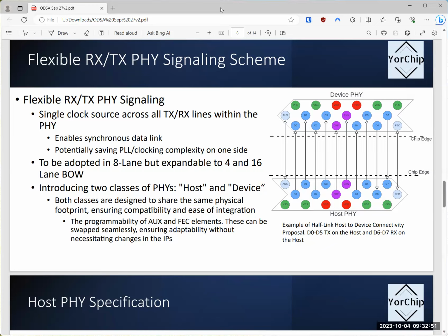The 2 caveats are that there are 2 extra bumps, so it's 12 bumps instead of 10, and that the first step in the spec may not be one side taking the recovered receive clock and looping it back in to create the transmit clock. Somebody could just decide to do that. It's just that speccing that is much more complicated.